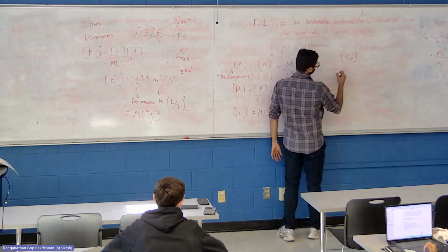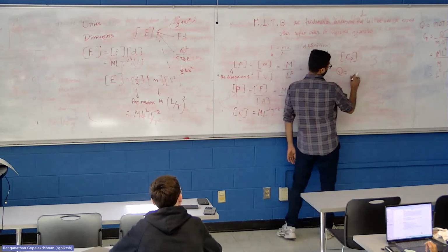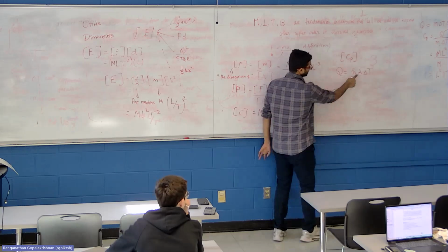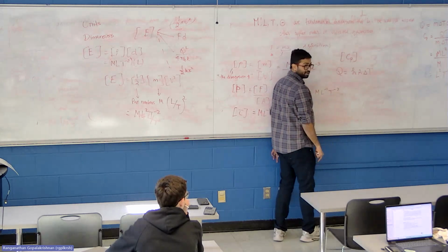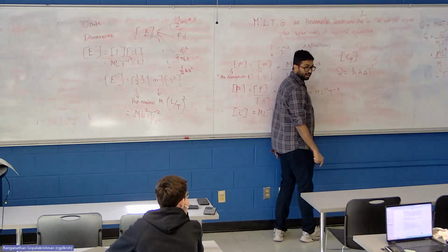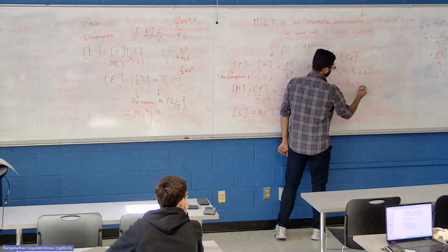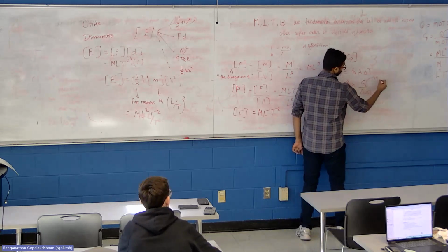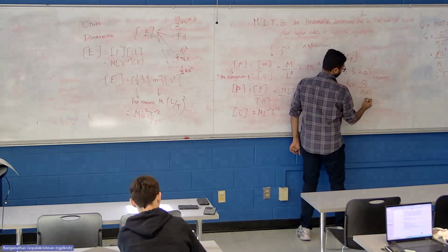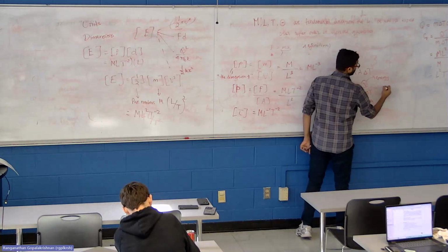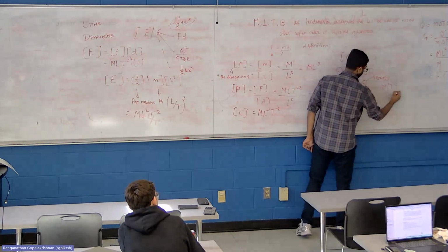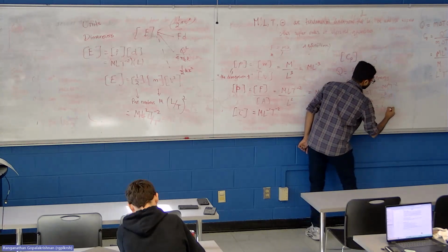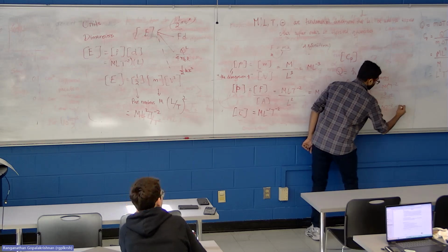So heat transfer coefficient is Q equals h A delta T. The amount of heat supplied to a surface produces a temperature difference. The proportionality constant is called the heat transfer coefficient. So h may be measured as Q divided by A times delta T. So this is energy or heat supplied. This is surface area. So this would be M L squared T power minus 2 divided by L squared times theta, which makes this M T power minus 2 theta power minus 1.